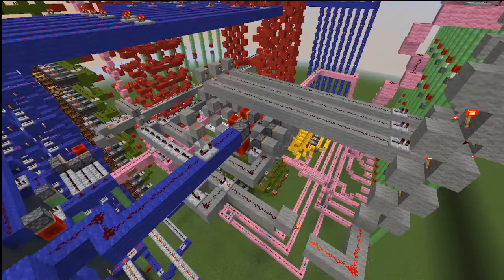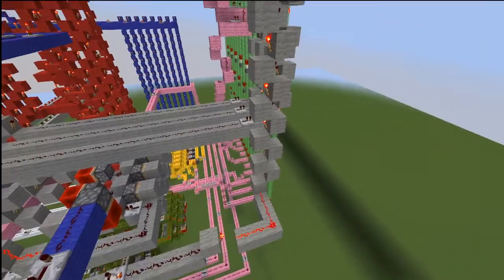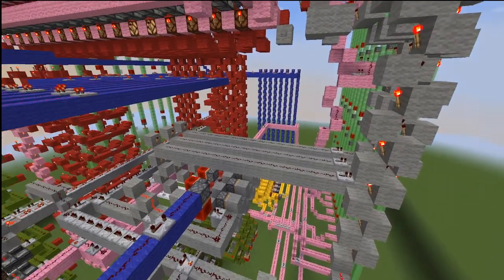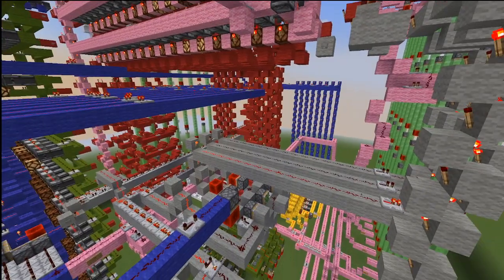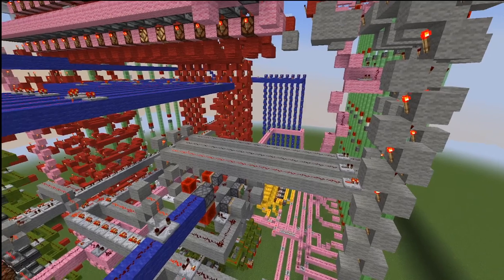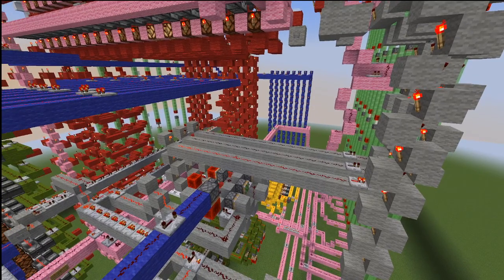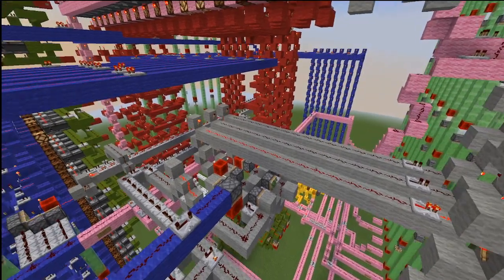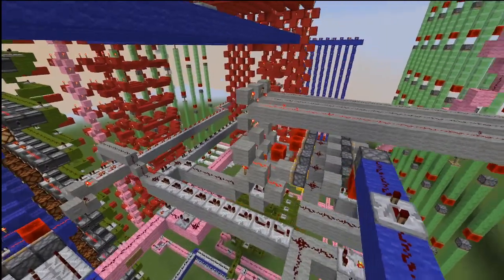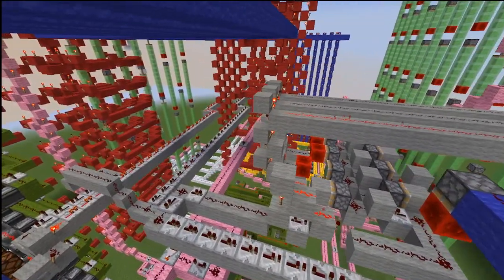It's going to perform a jump next, because if you remember from the program I showed, we had those data lines, and we don't want those to execute as normal instructions and normal code. So we want to jump down to line 8 in the program so that we can have our no operation, our out, and then our halt. And so when this clock pulse comes around, we'll start the macro instruction for jump.